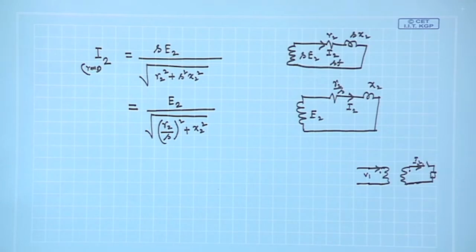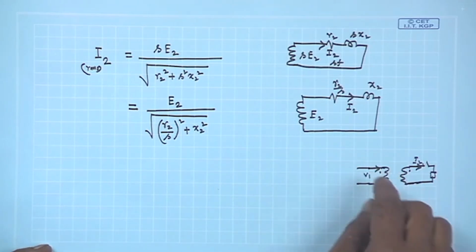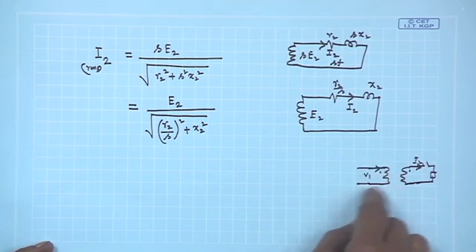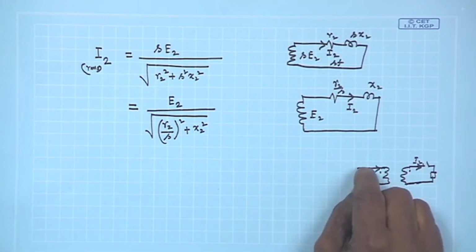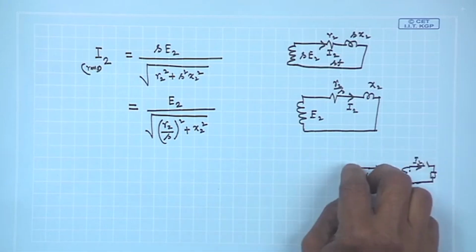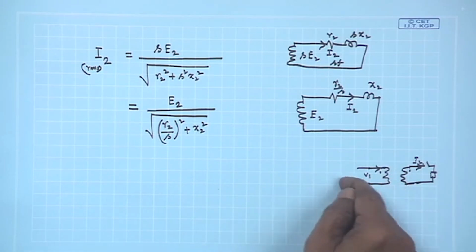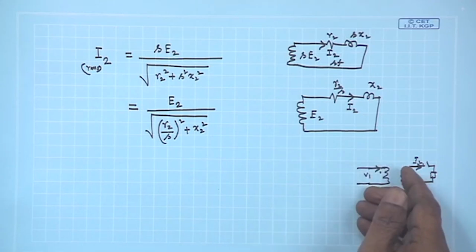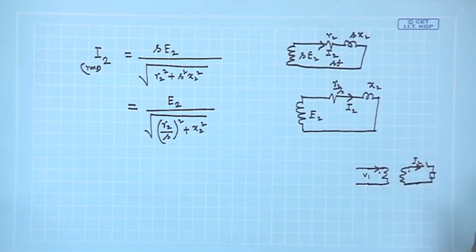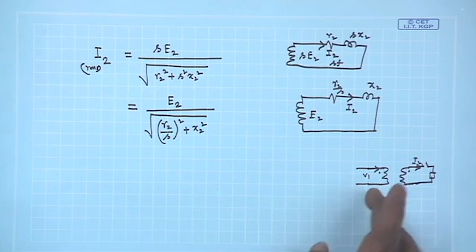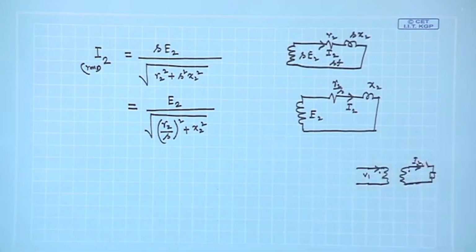Why can that not change? Because the supply voltage, the KVL is to be satisfied here in this winding. Applied voltage minus small r1 x1 drop, which suppose you neglect. So the EMF here gets fixed by this V1, nothing doing. No matter whatever you are doing on the secondary side, you are shorting, you are closing, some resistance, some inductance, do whatever you like, the net flux in the core will not change. That is why people say MMF balance, N2 I2 is equal to N1 I1, reflected current.